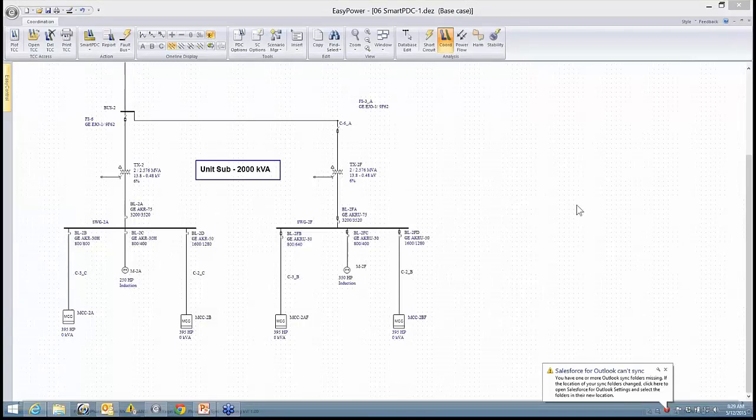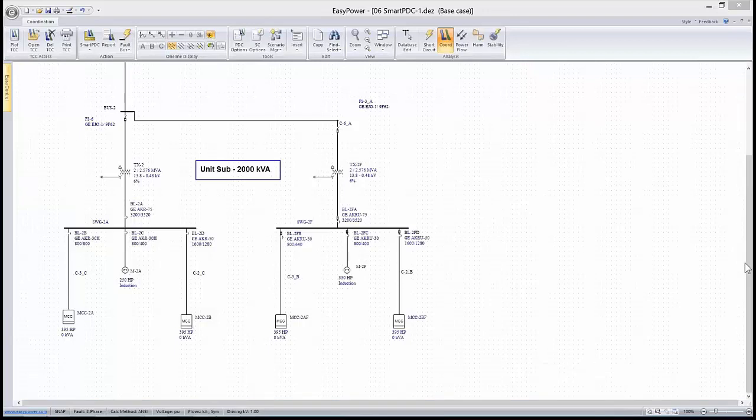Okay, the question: with a breaker on both the primary and secondary of a transformer, when a fault occurs downstream of the secondary, can I show how they interpret the reflected current on the primary of the transformer with respect to which OCPD will trip first?